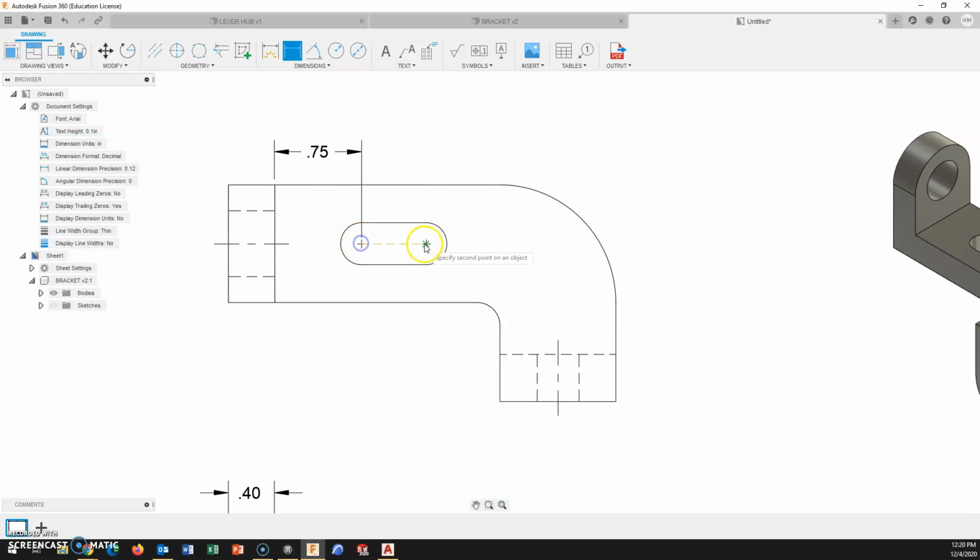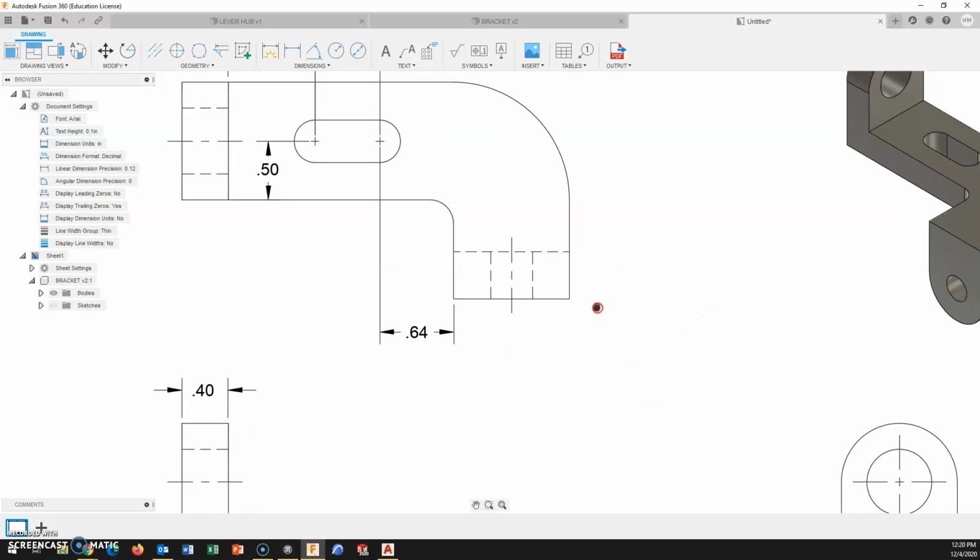Center to center, center to center, center to this edge. So dimensions in between the arrowheads. Let's just continue with the slot. We cannot assume that the feature is centered. I know we'd be dimensioning on the object here, but if I brought it left or right, long extension lines going through multiple object lines, dimensioning this on the object would be the better option. Okay.